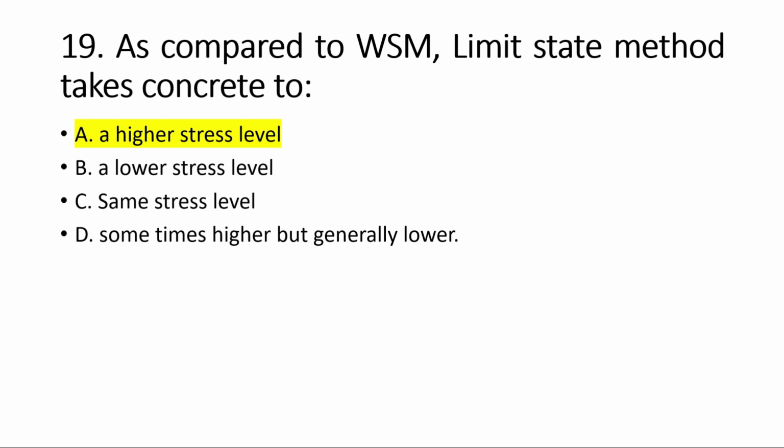As compared to WSM, the limit state method takes concrete to a higher stress level. As we know, the material factor of safety in the limit state method of design is less as compared to that of the working stress method. So for the limit state method, it leads the concrete to a higher stress level. Okay, so option A is correct. Next, move on to the next question.